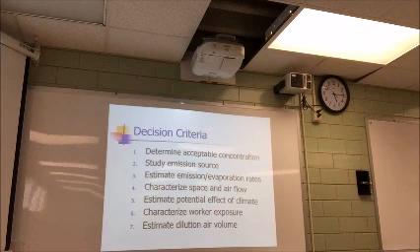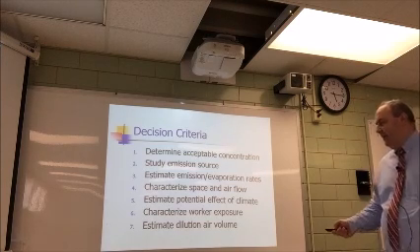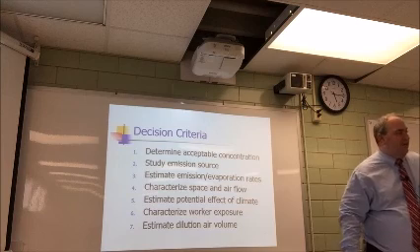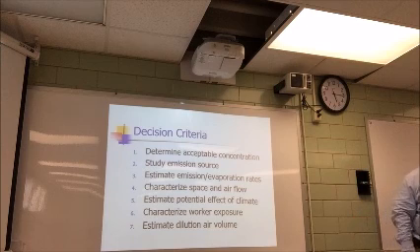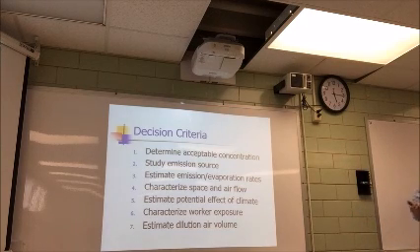same slide we used. Here's your decision criteria. I want you guys to think about what we're saying. When would you use dilution ventilation? Yeah, non-toxic. And you're going to determine what is an acceptable concentration. You're going to study the emission source. You're going to look at evaporation rates, and all the way down through there till you estimate how much volume you're going to need. These are the steps. Guys, again, this is what ACGIH, it's what all industrial hygiene decisions are made on. Okay?